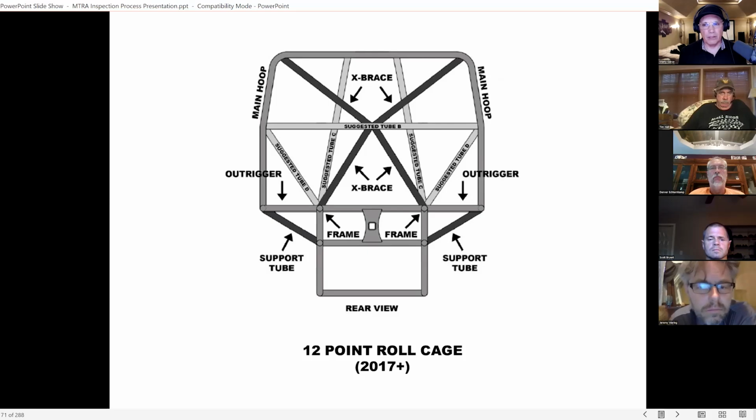But these newer, heavier trucks, those outriggers will fail, because you take a hit on the corner, it'll push that down. So it's important that force is carried all the way through, where you have this continual load being transferred from one tube to another. You don't want dead ends. You don't want a tubing ending in the middle of another tube, because it'll punch right through it.